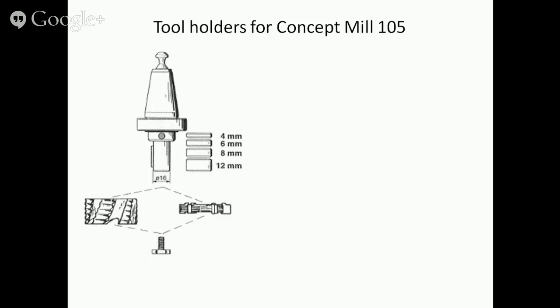There is quite a big variety of tool holders on the market. Let's first analyze the tool holders for Concept Mill 105. The tool holder has a self-releasing steep taper shaft. A draw bolt clamps the tool to the spindle.